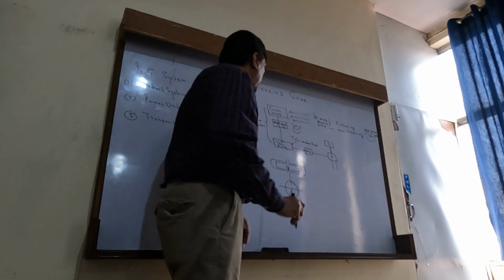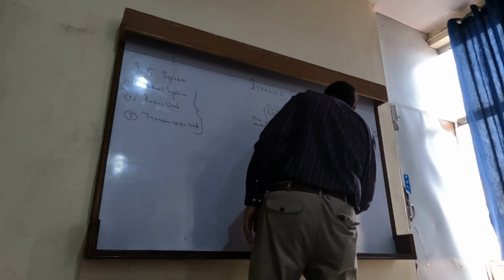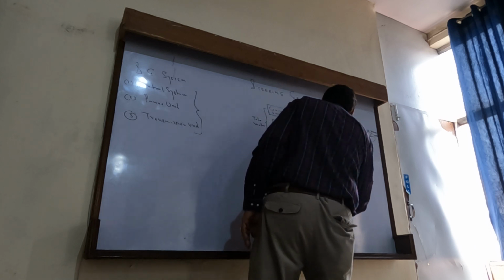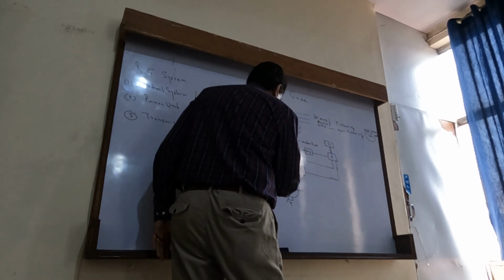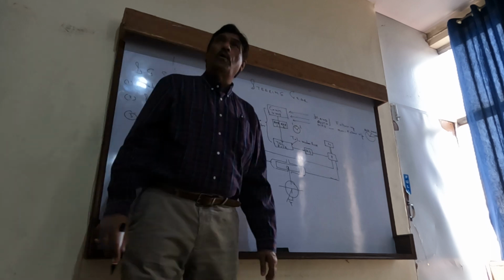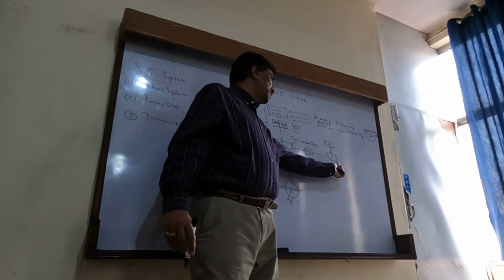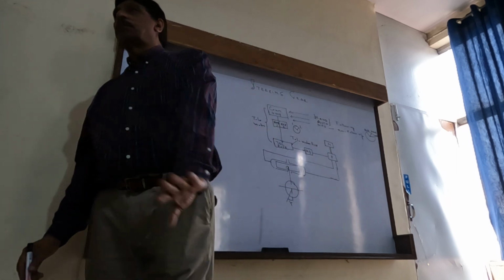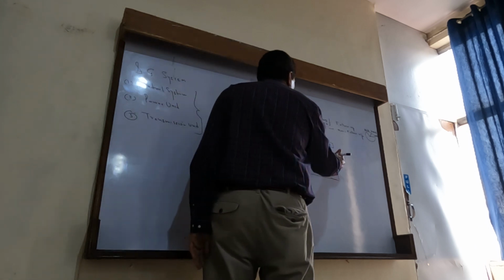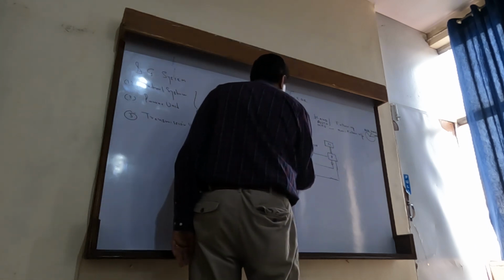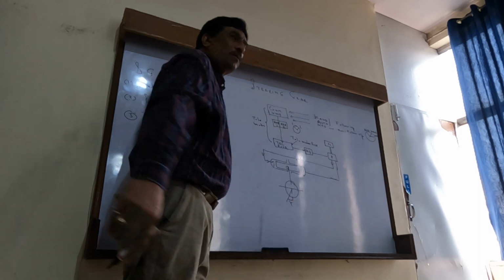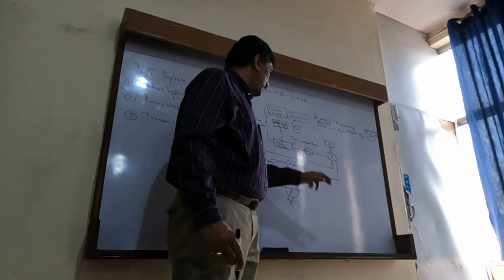Now these 2 lines, one is connected here, and one is connected to the other side. So this is the connection. Now always one of them will be high pressure, one will be low pressure, or one is supply, one is return. So let us see if this is the supply line, then oil will come from here, travel here, travel here, travel here, and act here on this side on ram number 1. This is ram number 1, this is ram number 2.